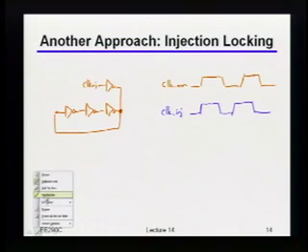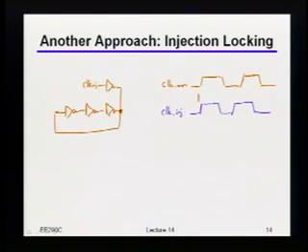So, okay, during this time, because I magically lined them up, nothing is really happening, right? But notice, on this edge over here, that injection clock is earlier than the main VCO clock, right? And hey, by the way, these two inverters with their outputs shorted together kind of look like a phase interpolator, right? So what is this thing going to do to the main clock? Which direction is it going to move it? Early or late? Early. Yeah, it's going to move it earlier, right?